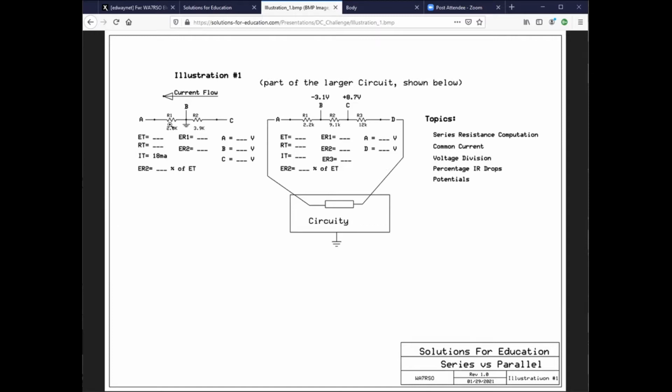First of all, if you are helping somebody, you're not just teaching how resistors in series add, but what you're also doing is you're saying, look, as current flows, it can go left to right, right to left, but also because the current is common between these two elements, it is going to then cause an IR drop, which is the key word for saying voltage drop. This 2K resistor and this almost 4K, that means that the voltage drop across this R2 is going to be proportional to this one here. In fact, mathematically, it's directly proportional. The voltage drop across R2 is going to be nearly twice as much as the voltage drop across R1, whatever it happens to be.